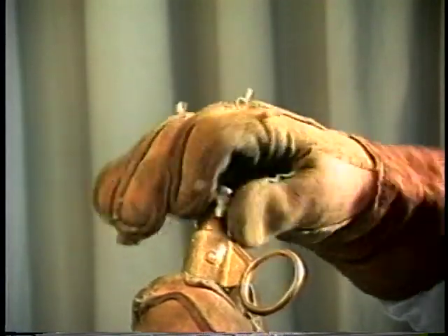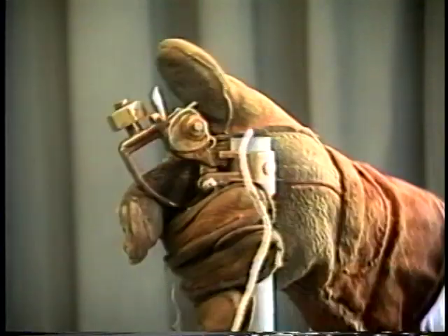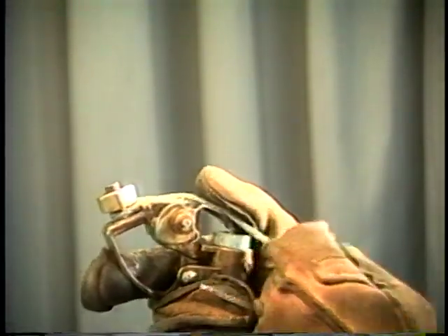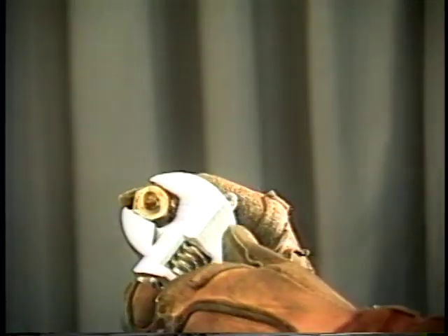Replace the barrel cap and tighten it with your hands until it is snug. It is recommended that you not use pliers or a wrench to tighten the cap. Turn the barrel over and arm the tensioner. Loop the tail of the fuse around the post snugly and then tighten the nut by hand. Then, use a crescent wrench to tighten the nut sufficiently.